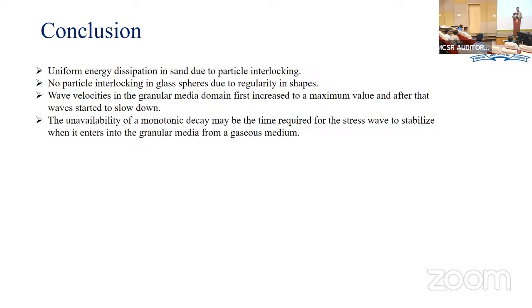For 43% RD of sand, we were getting 1.635 gram per cc, and for glass bead it was 1.62, that kind of density. And irrespective of how we pour the glass bead into the column, the density of the glass bead was always constant.